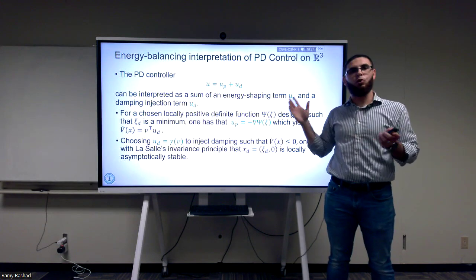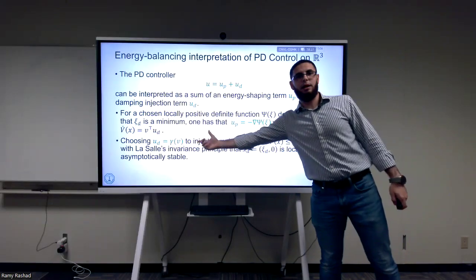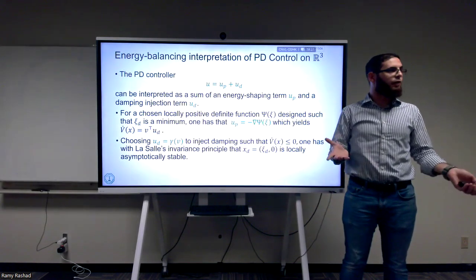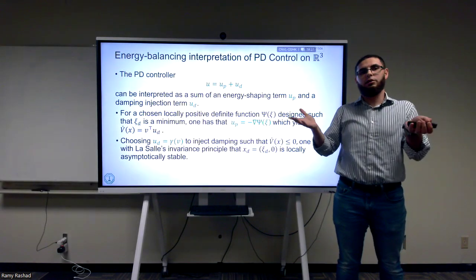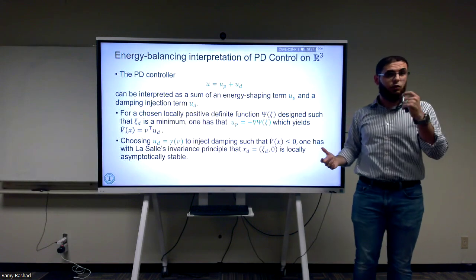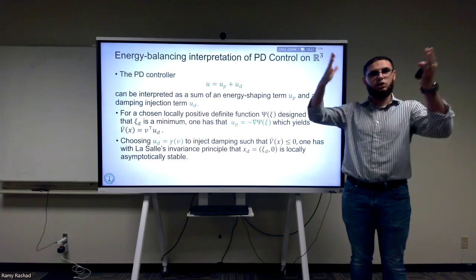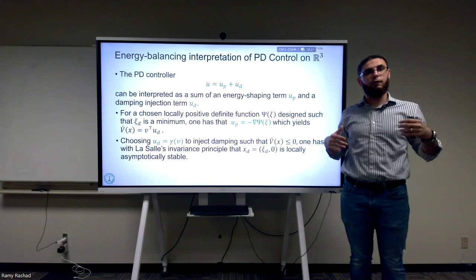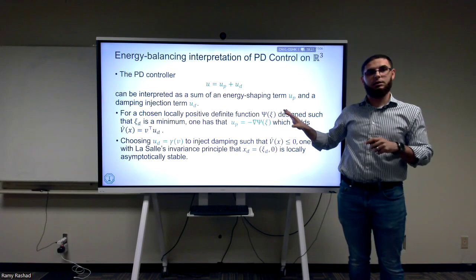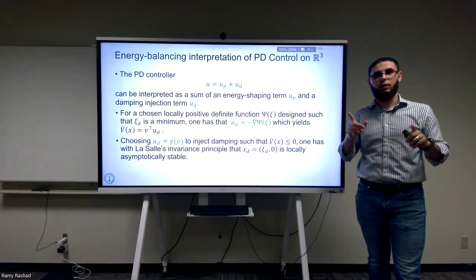And by the way, without doing any proofs, this is a theorem that is very general, right? No matter what the psi is and what the capital psi and the small gamma here are, no matter what these functions are, even highly nonlinear, we're still okay. We still conclude the local asymptotic stability of this equilibrium point. So no more analysis. This is just a general procedure. If you want to do PD control for any system, you can follow this process, okay, then we have it. Any questions?